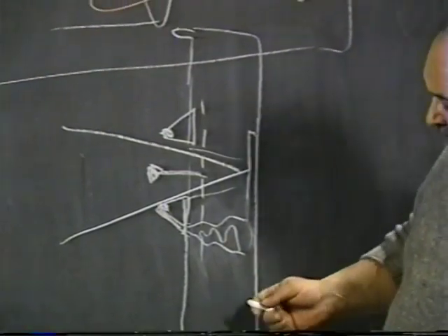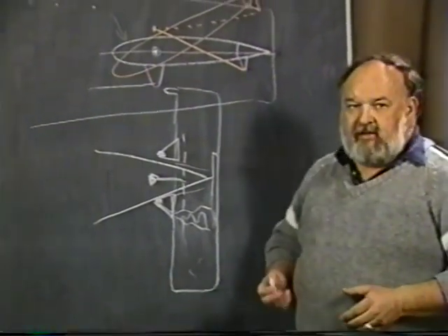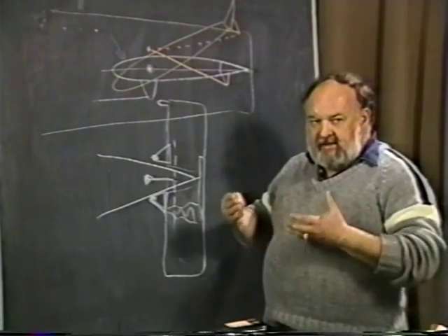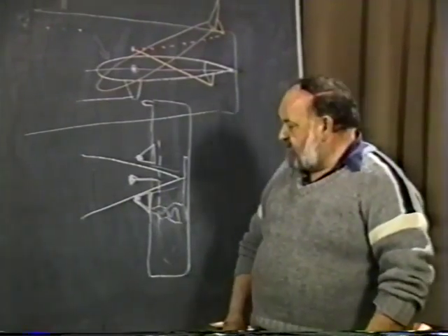Maybe if you got very high and very excessive, the outboard section might stall, but a major portion of the tail still had energy to it, still was producing a download, and it was not any kind of severe reaction where the airplane would then pitch over very violently as the tail surface would stall.